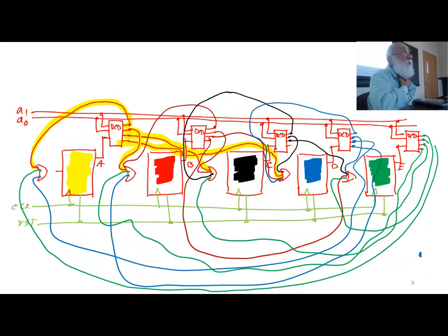Now what we need to do is to put the resetting and the outputs. The problem with the one hot is that you have to have the resetting, so that in this case I want to start with 0 0 0. I want to start with output 0 0 0 or state A. That means the same thing as I did before. I have to put a 1 in the first state and then 0 0 0 in the other states. So this is going to be my resetting.